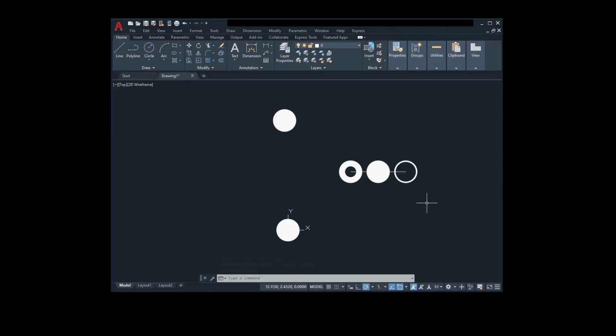This will give you concentric circles pretty quickly to represent washers or O-rings without having to draw circles with the circle command and then shade it in with a gradient or hatch it with a solid color. Instead, it does all that in one move, the donut command.